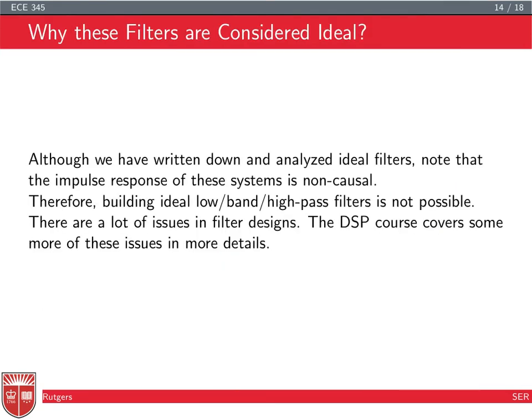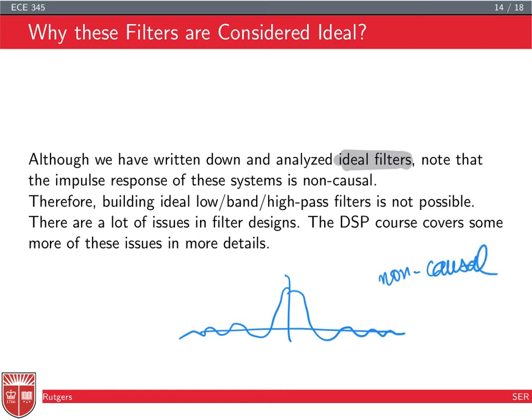So we have referred to these filters as ideal filters. The reason is that these LTI systems are non-causal. If you look at the sinc function, for example, even if you give an input at t equal to 0, you're going to get an output for t less than 0. So these systems are non-causal, and therefore we cannot realize them in the real world. You cannot have an output before the input.